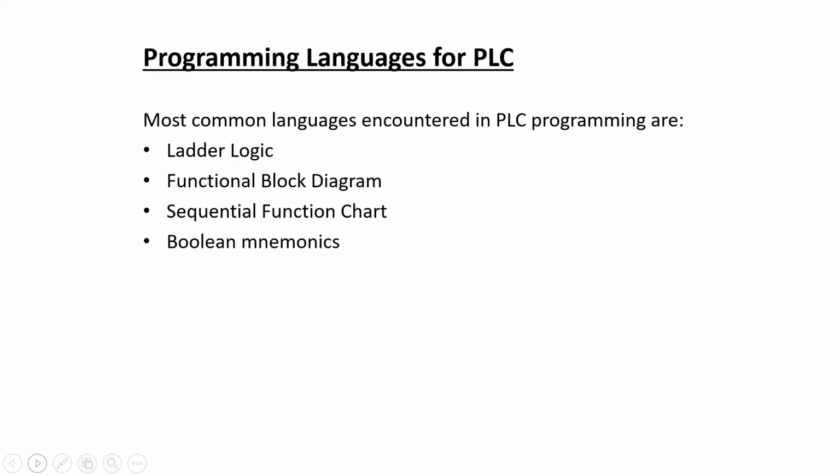Now, regarding the programming languages for PLC, the common types of programming languages which are used by different manufacturers are the ladder logic diagram, the functional block diagram, sequential function chart, and Boolean mnemonics. So we are going to mainly focus on the ladder logic programming because the PLC that we have in our lab is compatible with ladder logic programming.